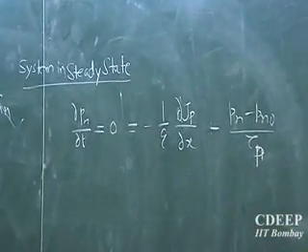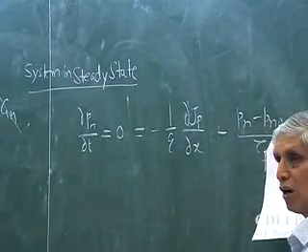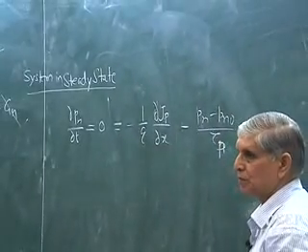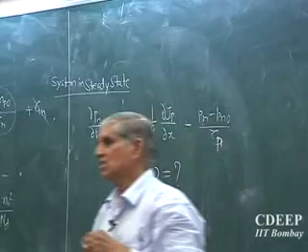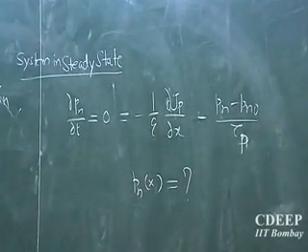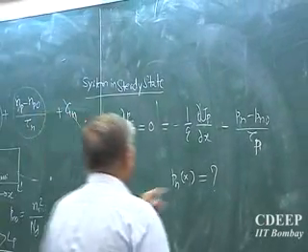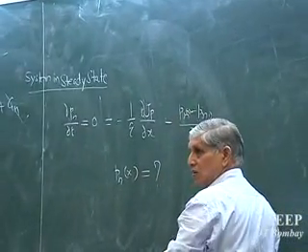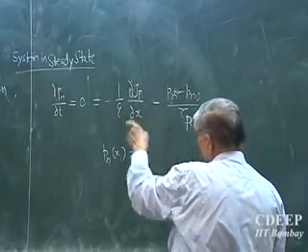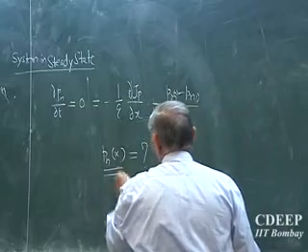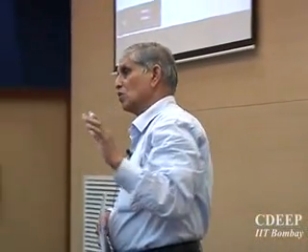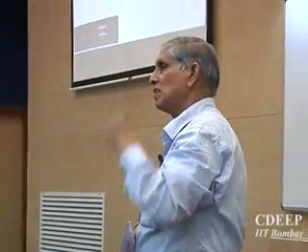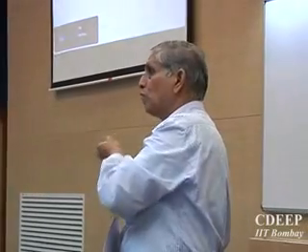So we say now, this is the diffusion equation, this is the recombination term, and we can solve this equation to get what? Pn, because our interest right now is how carriers go down to Pno. So from this equation, please remember what Pn is. Pn is the carrier concentration which is a function of x. Pno is the equilibrium carrier concentration in the entire semiconductor. If Pn(x) exists, dPn/dx exists, therefore a gradient is going to be set up, and if the gradient is set up, diffusion will start dominating, or start working. Is that clear? If Pn(x) is varying, dPn/dx is consistently there, so diffusion will follow this dJp/dx term.